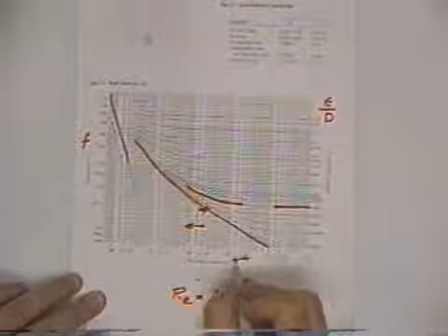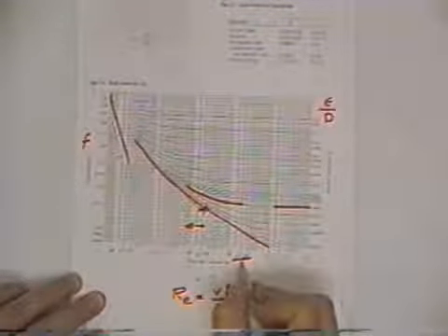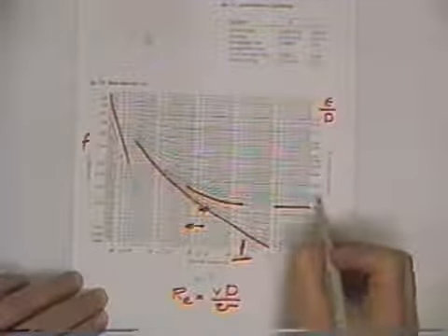And so we go back to our Moody diagram, and we've got the Reynolds number on the horizontal bottom scale. Ours is times 10 to the 5th, and it's 2.09, so it's going to be right in here someplace. Then we've got a relative roughness of 0.0017.